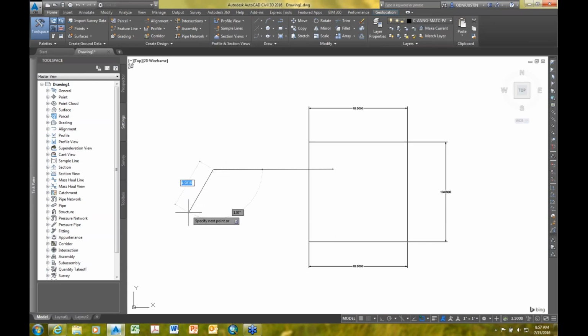And you can see that I can either program these in to a specific distance, let's say 5 feet. This line here, I want it to be perfectly straight, but it doesn't look like I got it real straight there. And if I want to go draw straight perpendicular lines, I can turn on down again on the lower right my orthogonal drawing tool, and I can draw that line in and have it be perfectly straight up and down 90-degree angles very easily. Okay, so I can kind of delete that out of there.